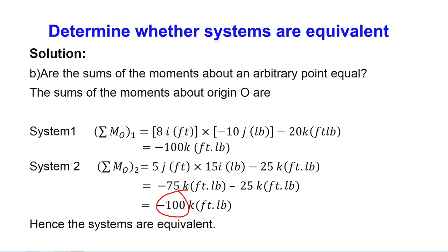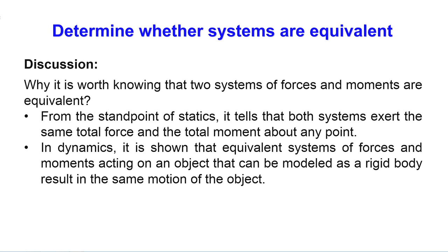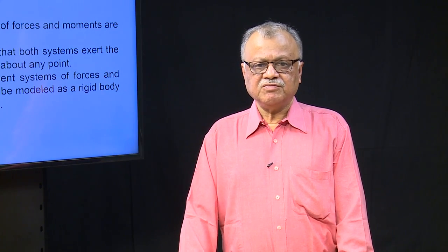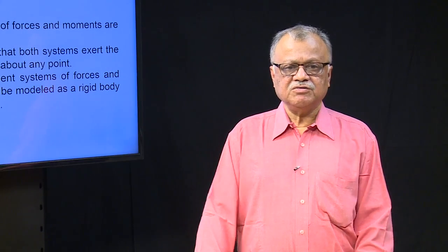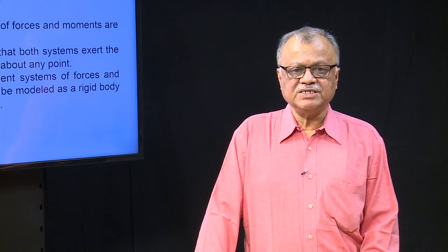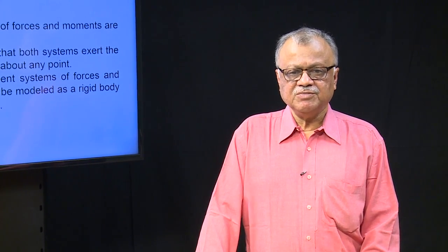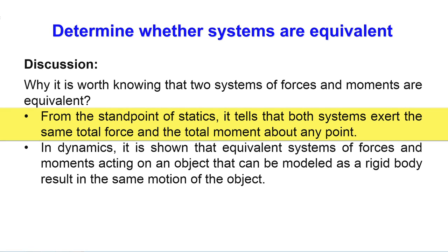So, thus the two systems are equivalent because the sums of the moments are equal and the sums of the forces are equal. Next, the question is why we want to find out whether these systems of forces and moments are equivalent. From the statics point of view, it states whether the system exerts the same total force or total moment about any point.